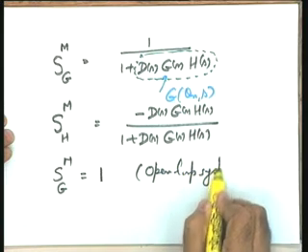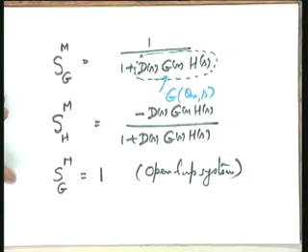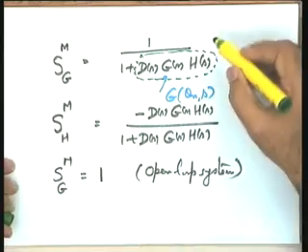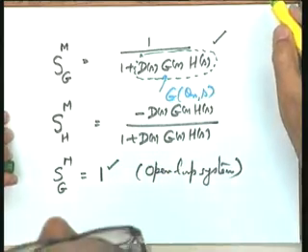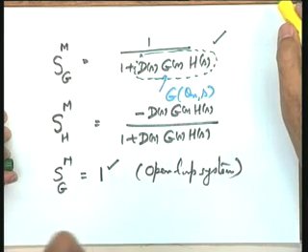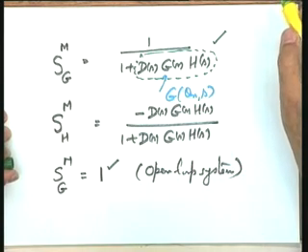When you break the loop, then the sensitivity of the open loop system is unity. That is, the open loop system is highly sensitive to parameter changes in the plant. So if I increase the loop gain, you please note that sensitivity reduces with respect to this sensitivity. This is one of the important attributes of feedback control.